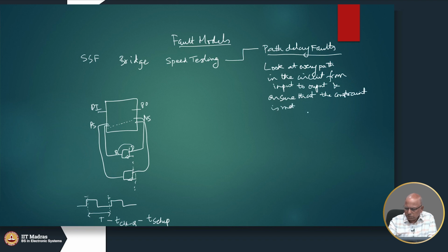This is a timing constraint: T minus T clock to Q minus T setup.